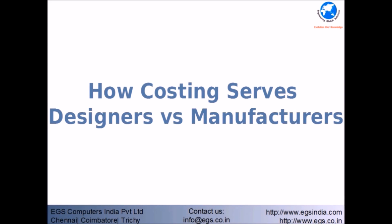How costing serves designers versus manufacturers. For designers, costing provides estimates of how much parts should cost to manufacture. Costing can compare models so you can make decisions based on cost earlier in the design process. You can try what-if scenarios such as removing features, changing materials and using different manufacturing processes to see how this affects the cost. The cost estimates are repeatable because the results are based on the data in templates, so you can always use the same template information to calculate the cost.